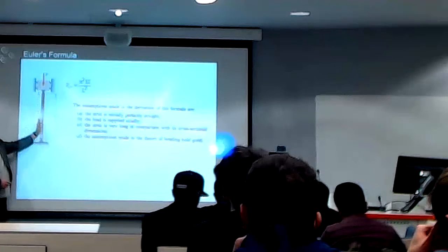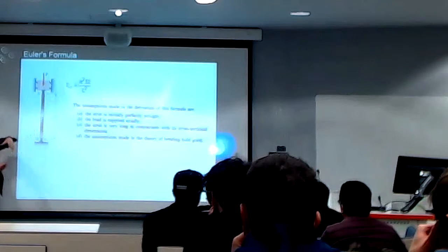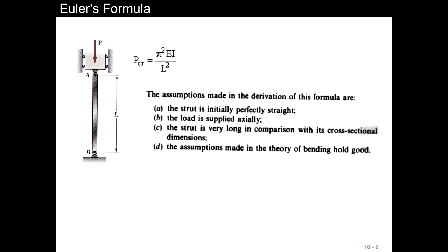And things aren't perfectly straight. Like if you design in steel, you're allowed to be out 5 millimeters. If you're in concrete, you're allowed to be out 50 millimeters over a number of stories, and that will always give you an eccentric load. Eccentric is just off to the side, so there's always a moment.